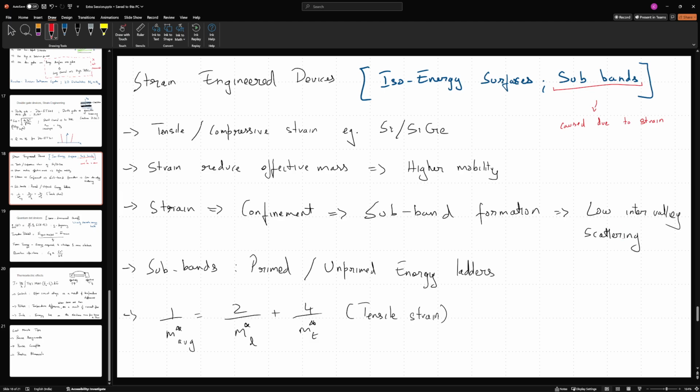Now remember, intervalley scattering implies potential direction change in an electron. Well, that's what scattering means. So I hope you understand that. Scattering means that an electron moving in one direction turns to another direction. Now, because I'm creating these subbands with distinct energy levels and different electron mobilities, electrons of one mobility will stay in the same band and therefore they will have the same velocity. They are very unlikely to change their velocity, which implies if I have a potential that drives them from source to drain, they will continue to move from the source to the drain.